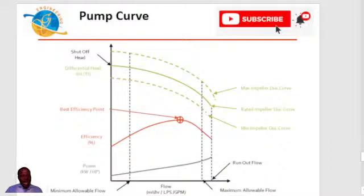So if you look critically, as your flow is increasing for a given centrifugal pump curve, what happens to your differential head? Your differential head is reducing as your flow, or the pump capacity, is increasing. In the same way, as your pump flow is reducing, the differential head, or total head requirement, is increasing.